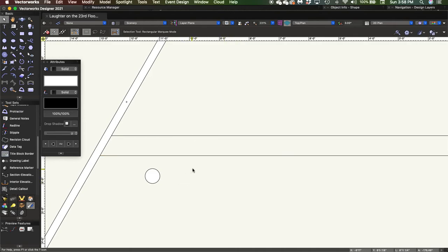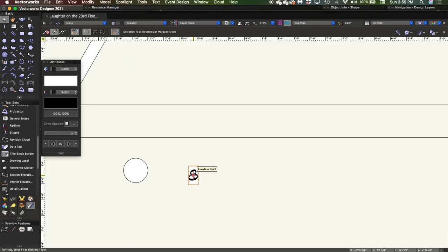And then I'm going to create some text. So again, activating the text tool in the basic tool set, I'm going to hit number 1. That's my shortcut. Gives me my cursor. Click once to place it. This one is going to be 8 inches, so I'm going to type in 8. Escape once to get out of it. X to get to my selection tool. And then I'm going to move my 8 into the center of my circle.